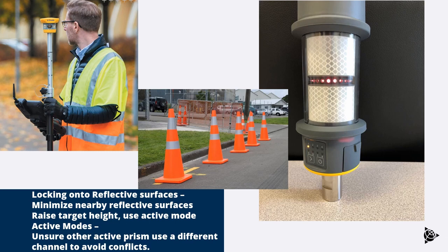When in active mode, make sure that the total station locks onto the correct target by making sure any other active prisms on site are using a different channel.